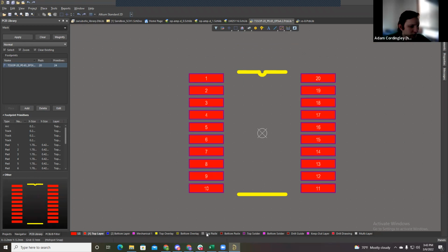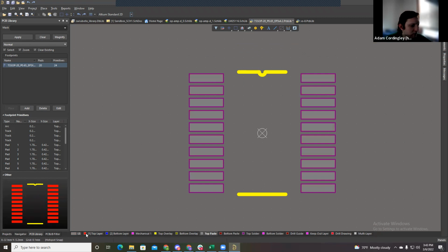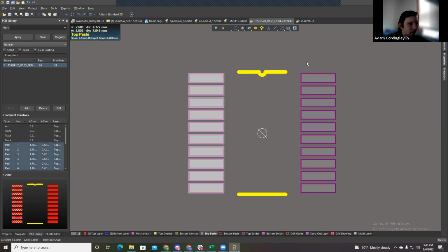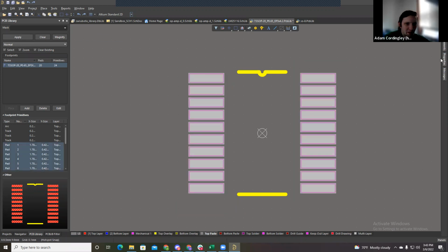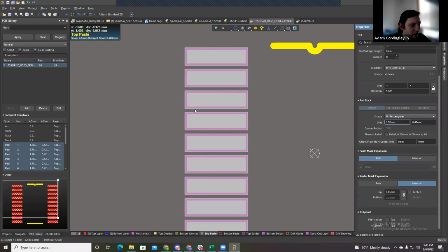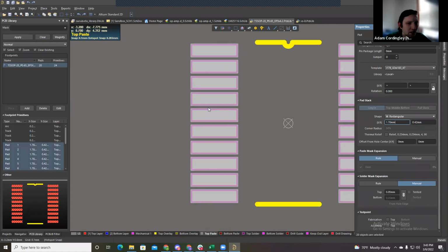Oh, I just forgot. Here's the other thing we need to do with these pads. We did the solder mask openings, but now we need a paste mask opening. So the paste mask, for those who are unfamiliar, is that stencil sheet that we buy from the PCB house, with cutouts so that you can spread solder paste really easily. The amount that's on there by default will be a little bit too much, and especially on a fine pitch package, it's going to tend to blob across if you leave it like this.